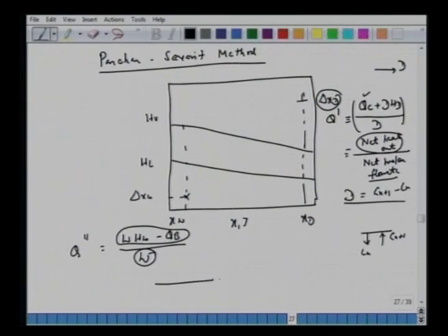So for any bottom tray we have g m plus 1 and the liquid leaving is l m, so the difference is the same as w here. So the definitions for q dash and q double dash are the same, net heat out over net molar flow rates. Okay. Now what happens in our case when we have this open system?